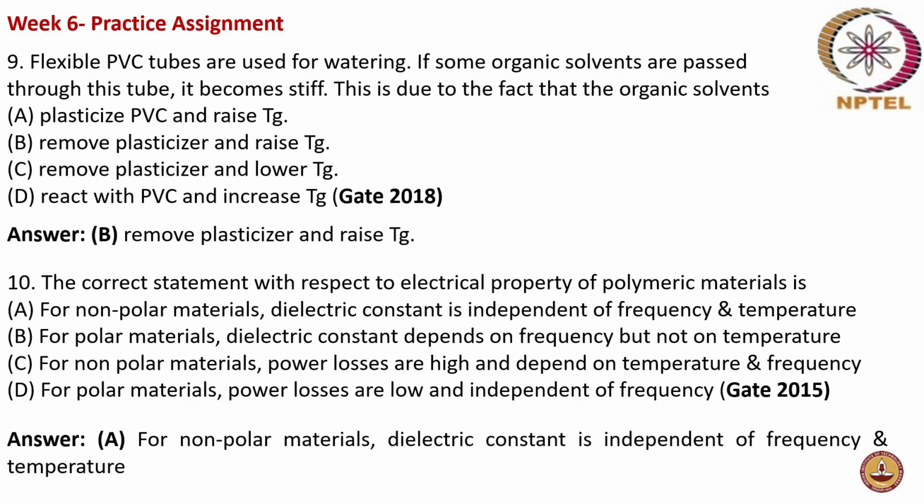Actually, the answer is: for non-polar materials, dielectric constant is independent of frequency and temperature. Option B is not correct because for polar materials, dielectric constant depends on frequency as well as on temperature, because temperature also affects the polarization. Similarly, the frequency, the time scales. Whereas in non-polar materials, there may be some residual dielectric behavior, which doesn't depend on the frequency or temperature. So that is the only correct statement, whereas the remaining are not correct. Okay.